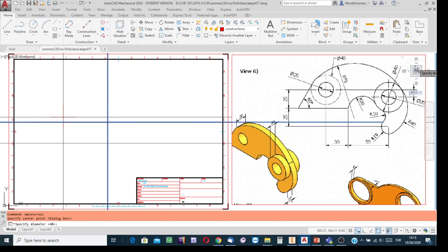Diameter, here this number you see is the same, 40. Write 40, to have the axes not only for the outer circle but also for the inner circle. Partially, the axes of symmetry will also be the axes of symmetry of the inner one, as these are concentric. Shall we create the axis of symmetry for this part? At the following stage, although there will be a full circle, after trimming it is going to be a circle arc, not a semicircle, not a full circle.